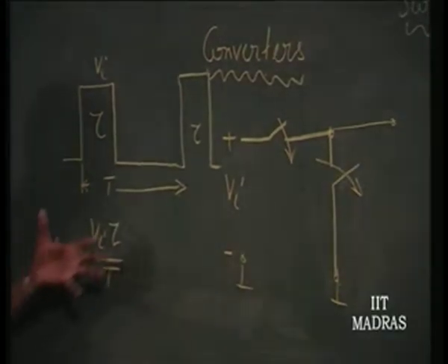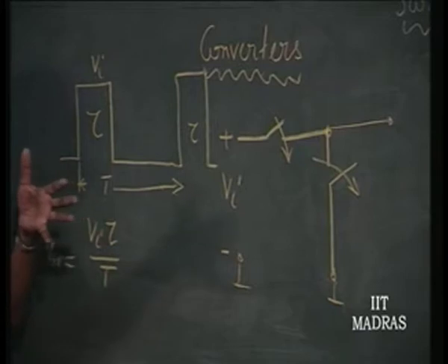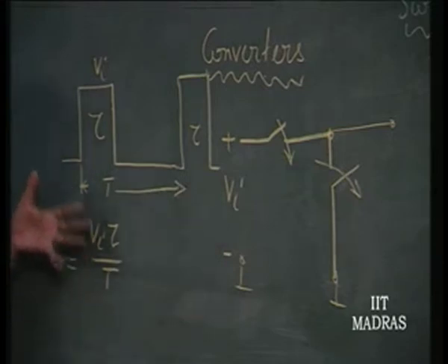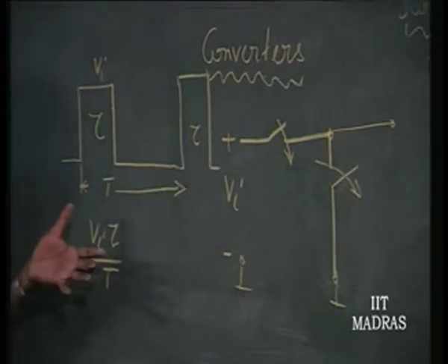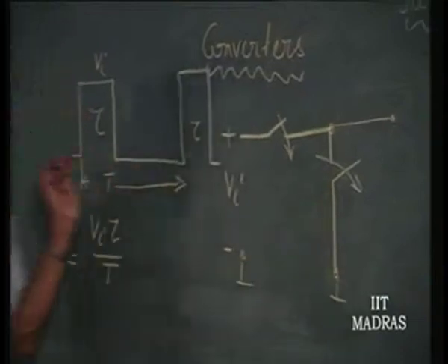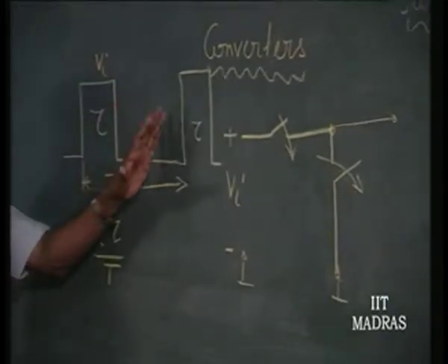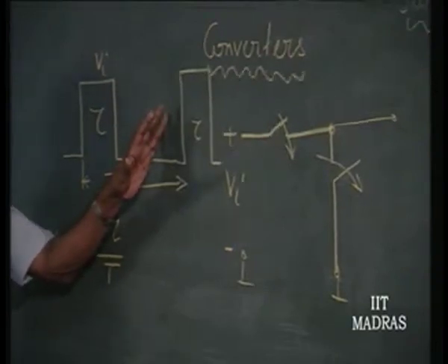So, this is a very efficient converter so far, right. But how to obtain the average? The waveform obtained here is this. Do you understand this? The waveform is still having all sorts of ripples, right. So, we have to get rid of the ripples. How do you do it? You have to put a very efficient low pass filter.